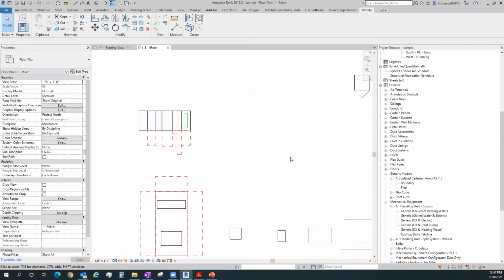And maybe you're like a custom kitchen equipment manufacturer rep or something like that, and trying to put in a brand new super domed pizza oven or something crazy. Again, you could build a placeholder family that is the right shape for that. Does it fit in the building? You'll know, yes, you can get it in there based on your placeholder family, and even do some staging type stuff with placeholder families with Navisworks if you want to. So there's lots of reasons to use a placeholder family in that case.